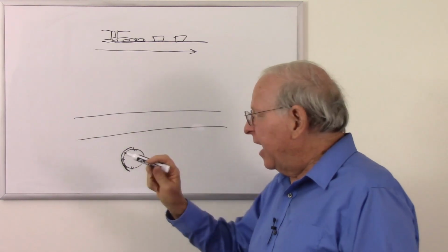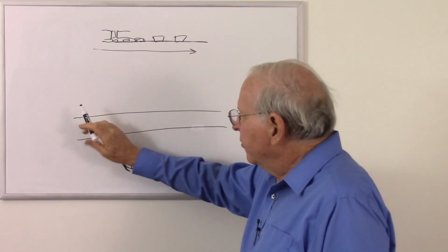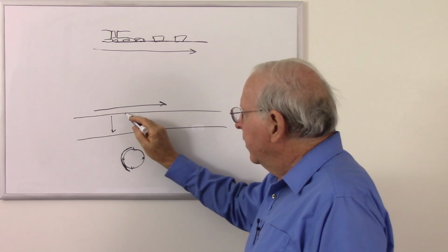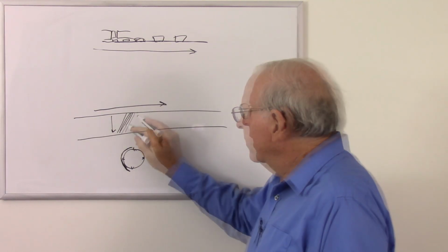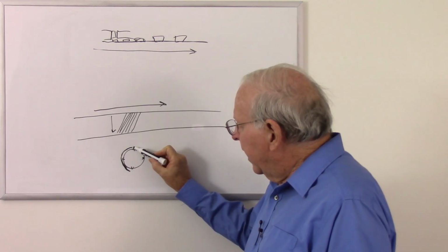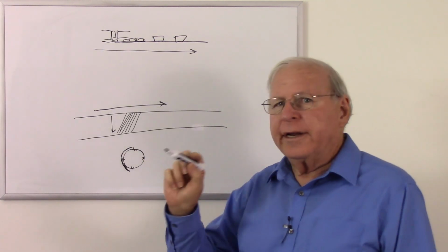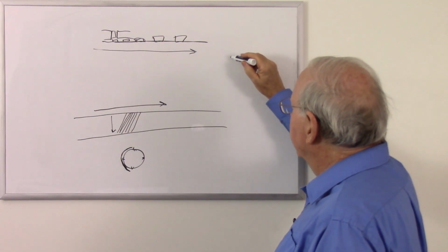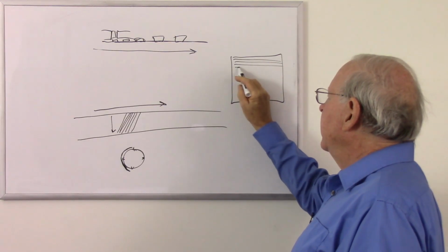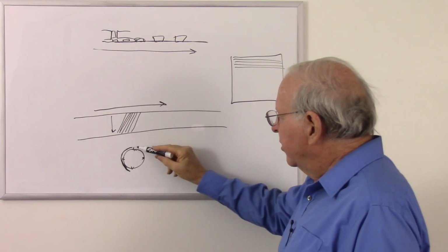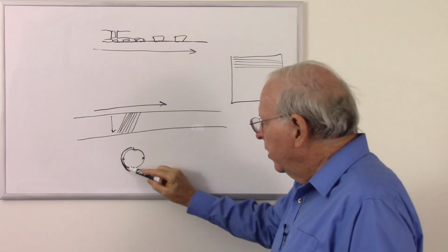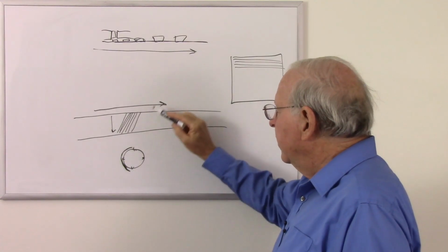So instead of moving the tape fast, we moved the head across the tape. And since the tape is moving and the head is rotating, we would actually end up with tracks across the tape in a diagonal path. In the early systems, each pass of this head across the tape would cover 16 lines across the screen. So here's our screen over here, and we have those lines going across, painting the image, and we would put 16 of those on each one of these little tracks here. So each head 16 lines, so one spin of the head would do 64 lines of television.